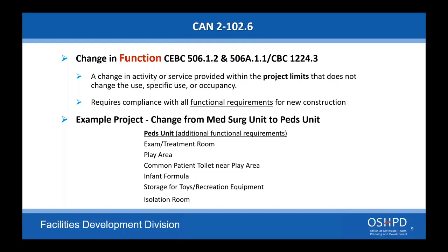So if you have an old fire alarm system in the building and that's what's being served, and you're doing accessibility upgrades, there may be an alternate method of compliance required to keep the existing fire alarm system. The intent is not to make you replace an entire fire alarm system because you're upgrading one room. So I would definitely, again, make a phone call and talk to your region supervisor.